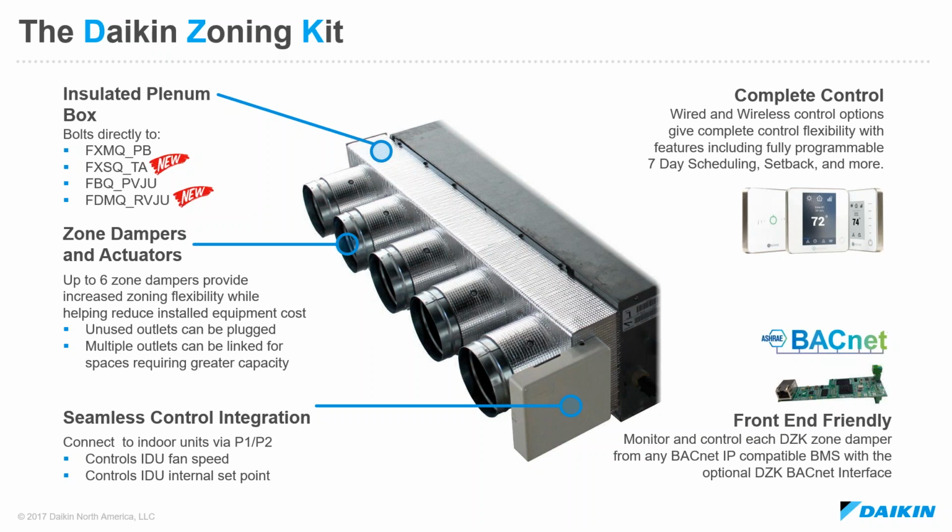In the first iteration of the DZK, we didn't have that capability to monitor and control individual outlets. So as the DZK has evolved over the years, we've integrated this optional BACnet card to get that additional level of control from a front end.